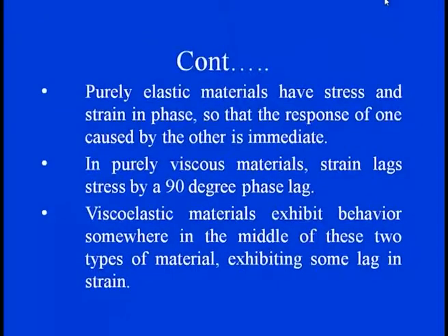So, in the viscoelastic material we have the elastic material property with no phase difference, and we have the viscous properties with the 90-degree phase difference between the stress and strain. So, viscoelastic material exhibits behavior somewhere in the middle way, when both types of properties are creating their dominant features.